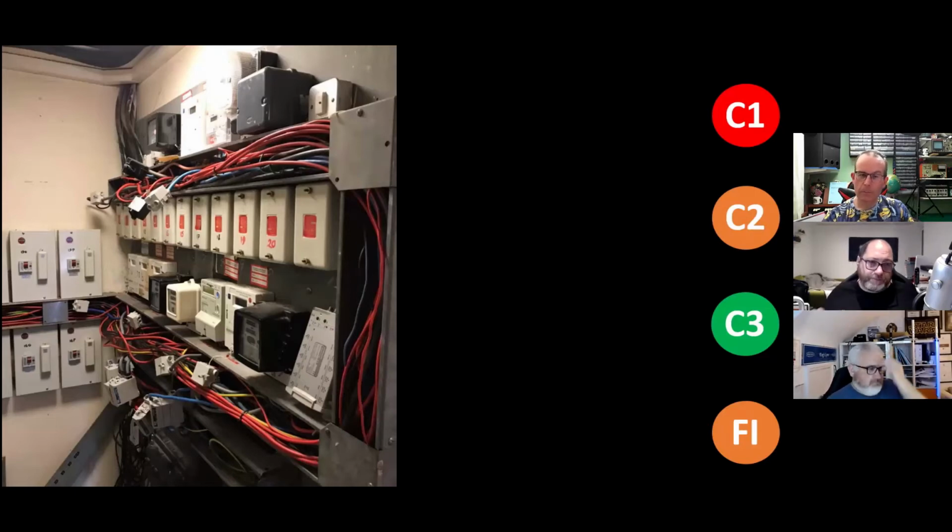Okay. Intake cupboard. This is a DNO installation, but would be now considered BNO, building network operator. Cutout is right at the bottom. And this is, well, it's just a mess, isn't it, really? What would you code that? Look at it. Henley blocks hanging out the trunking. This has just been so badly altered and added to over the years.